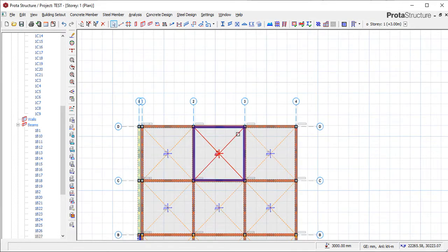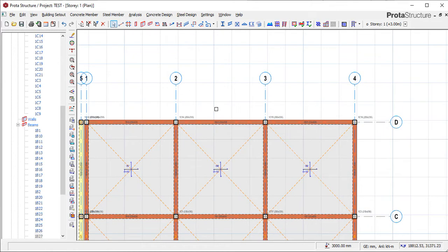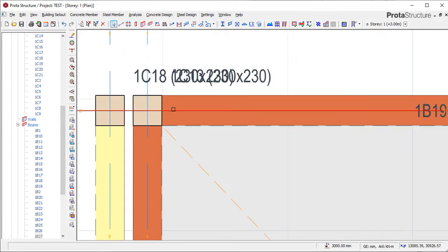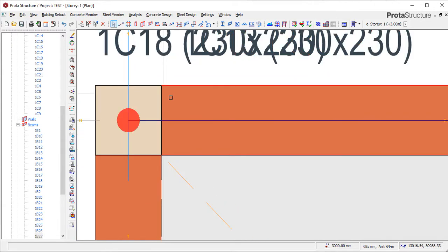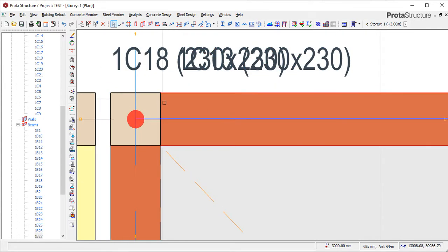But whatever it is, you can start a fresh drawing from the beginning, close that sheet, open a fresh one, and run through it again. Check most especially if there's a joint opening, your columns not touching, or the beams not properly connecting.